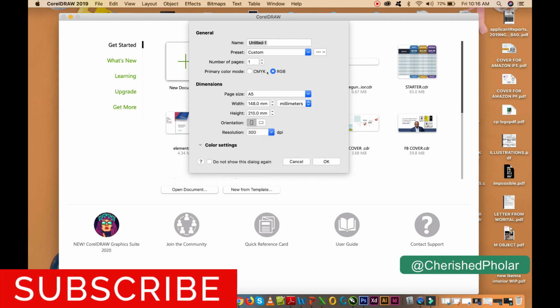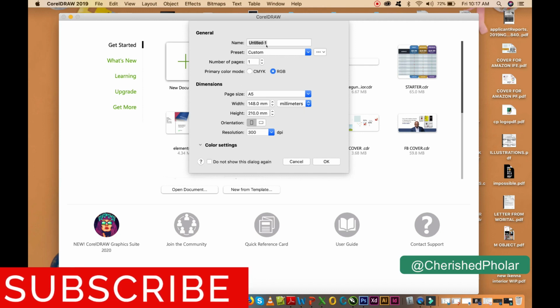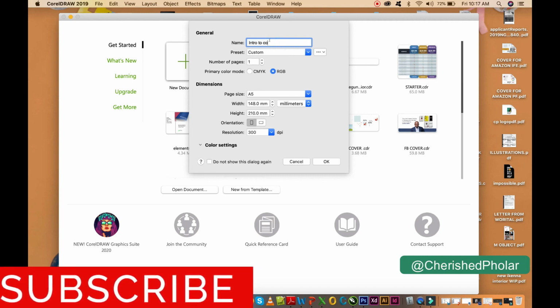All right, and here, if you are using the design on social media, online, and you're not printing, then it's better you leave it at RGB. But if you're printing, then it should be CMYK. Then, of course, you'll be changing the name there. So right now I'm going to leave it as A5. Then, of course, the resolution should be 300. And I'm going to rename this now. I'm going to call it Intro to CorelDRAW.